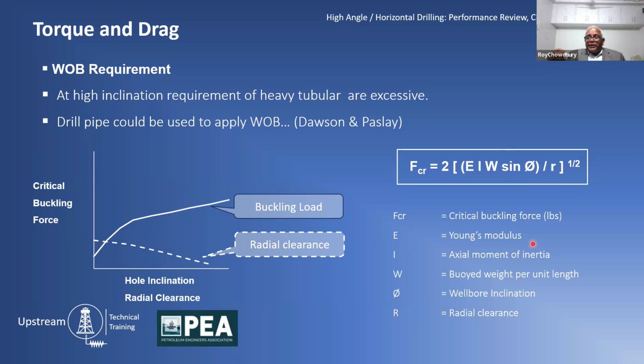Obviously, what it means is, as you continue to push this pipe through, all of a sudden you would go from sinusoidal buckling, which is buckling in one dimension, to helical buckling. So it is extremely critical to understand that yes, you can buckle your pipe sinusoidally to an extent, but it will spring into helical buckling immediately.